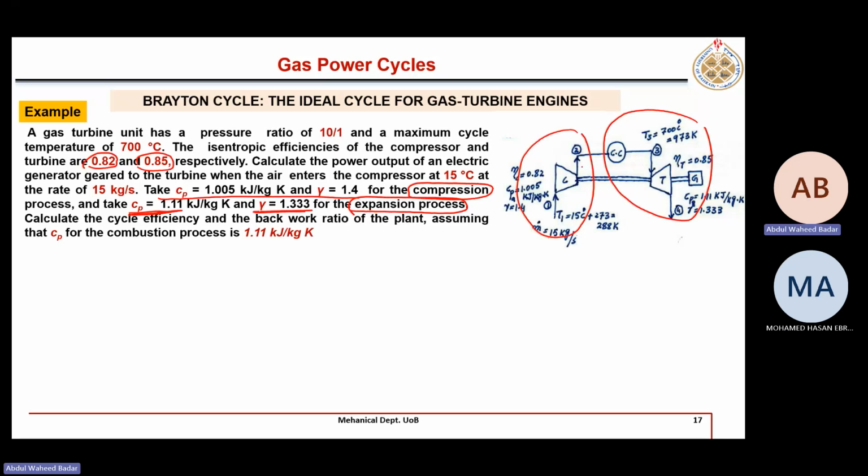For both, because here the purpose is work transfer, mainly work transfer. The heat production should be as small as possible. So that is in our hand: by using proper lubricant, the amount of heat which is produced due to friction should be kept as minimum as possible. So it should not be more than 10 to 20%. That's the typical value which we have. Okay.